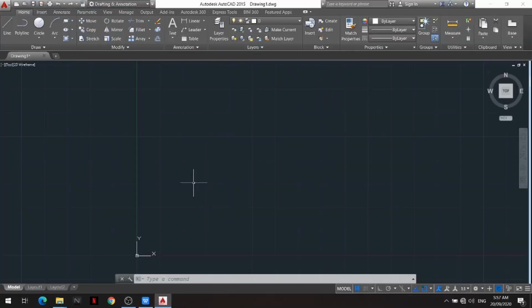Good day everyone. In this video, you will learn how to use the different drawing aids in AutoCAD. Specifically, setting grid and snap, setting the limits of a drawing, setting line weight, using Ortho Mode and polar tracking, using layers, using object snaps, using zoom tools, and panning your drawings. These different drawing aids will help you make your drawings in AutoCAD easier.